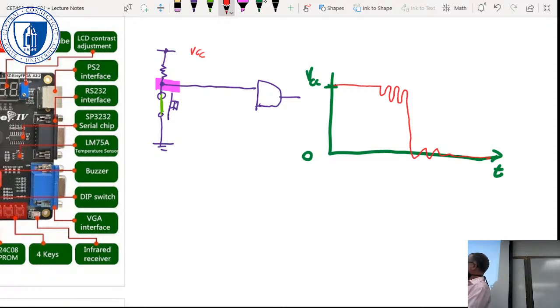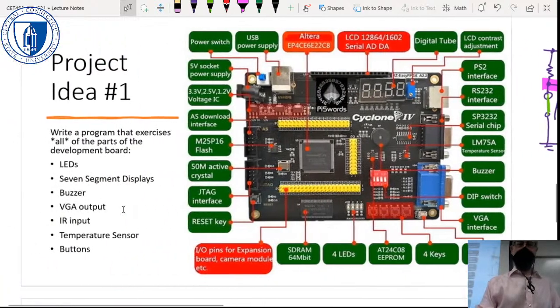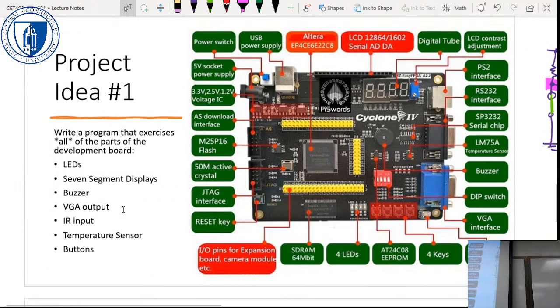And this is called bounce. So the reason I bring it up is I said the buttons were easy, but they're not necessarily that easy because of this bouncing problem. So one of the things you've got to do when you take inputs from mechanical switches on just about any digital device is put a bit of debounce logic in there, right?